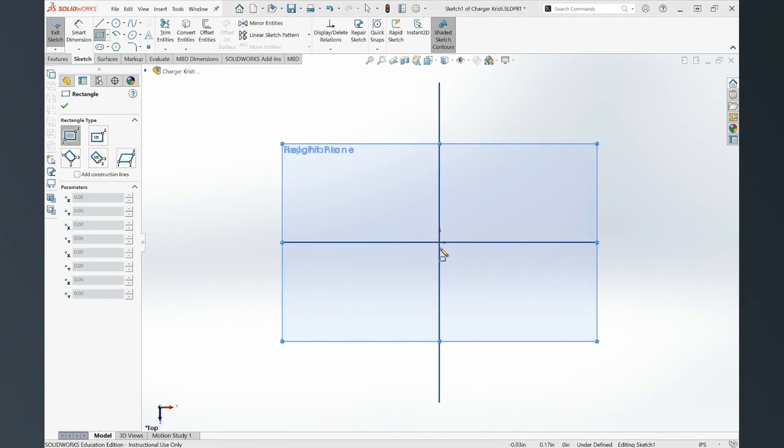This plane is going up through the middle of the screen, but right now it just looks like a line because we're looking at it straight from above. We do want to get our sketch coincident with this plane. So coincident basically means intersecting. And you can see whenever the pencil point is hovering over the plane, I now have this little yellow box that's showing, and the yellow box has the coincident icon in it. And the plane turns orange.